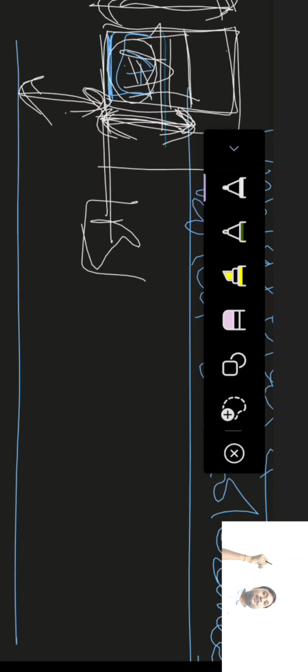When the tolerance zone can be represented on one side of the zero line, it is known as a unilateral tolerance. So for fundamental deviations from A to H, all the tolerances will be unilateral tolerances.